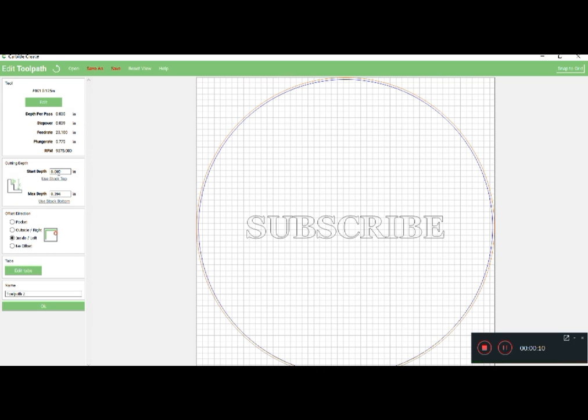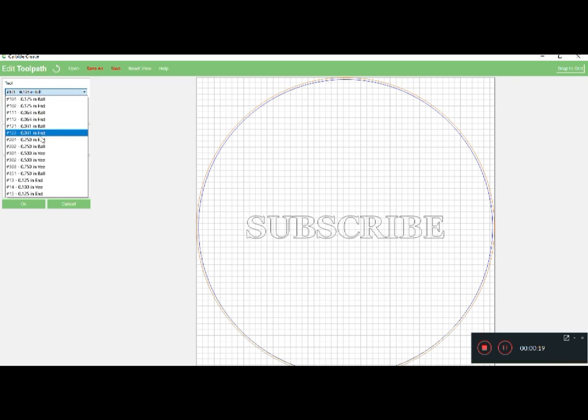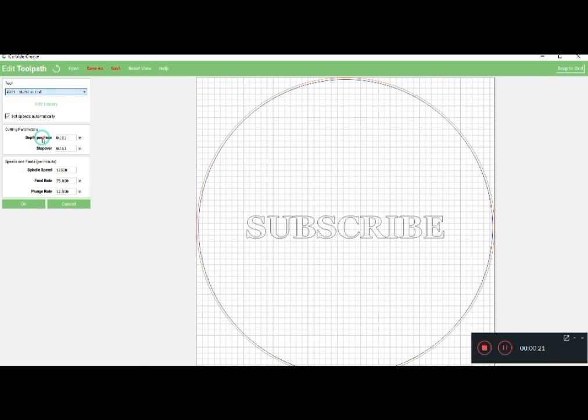So the start depth right here, max depth, I'll show you all these, how to set this up, but let's go to our bit first. So we want the 201. This comes with your machine, the 250 N bit, this 1/4 inch. Depth per pass and step over, we'll talk about this here in a second.